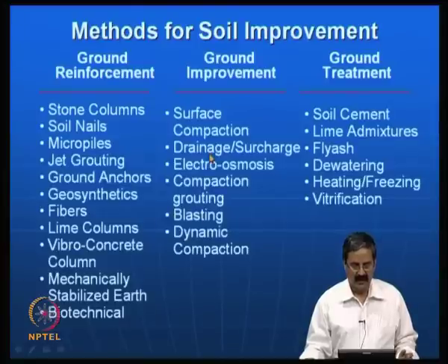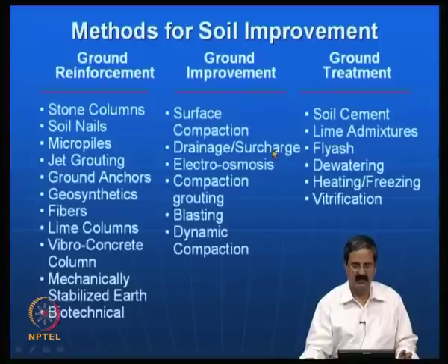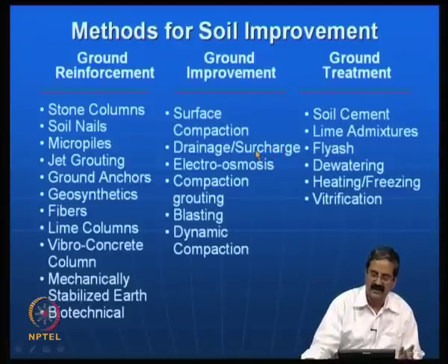Then, as I just mentioned, you remove water from the soil, and that leads to drainage, and because of the drainage or the expulsion of water, there is an increase of shear strength. One way of removing water is by putting a lot of load, what is called a surcharge or a preload. You will know the concept of pre-consolidation pressure. Below the pre-consolidation pressure, the soils will have less settlement, that is the standard thing. So, we apply a very high surcharge such that the existing load is less than the surcharge, with the result that whatever settlement or strength you want is achieved.